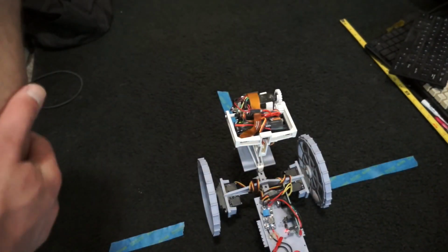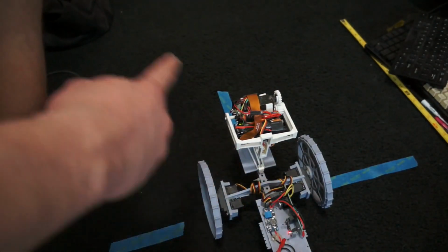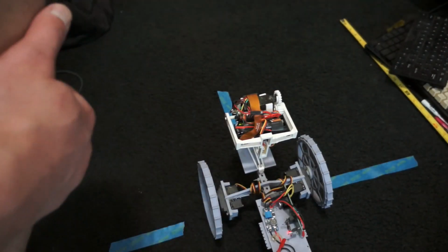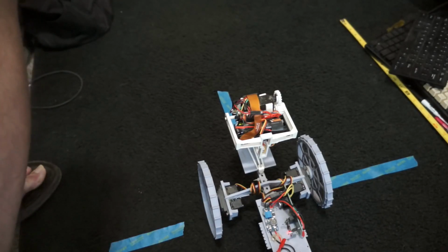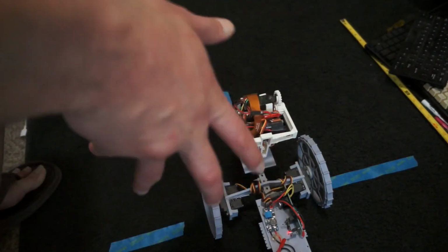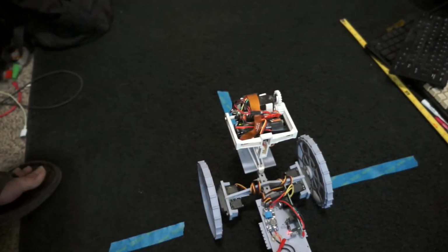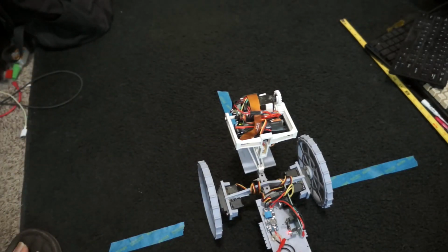I was trying to calibrate it to do left and right 90-degree turns, and it's annoying having to keep programming this thing, so I'm just going to make it where the WebSocket can tell the servos how far and how fast to move versus me having to program them in. But anyway, the point is, if you watch, it turns faster right than left, even though the degrees are the same, so that's the annoying thing I have to fix.